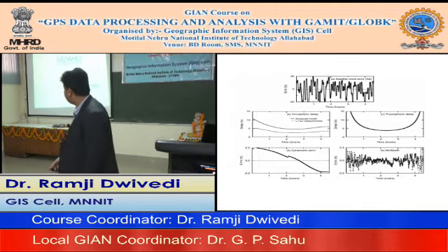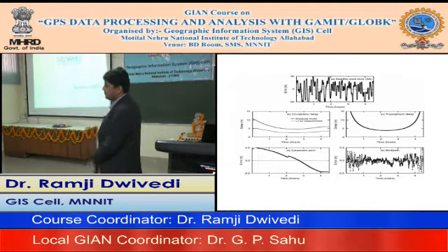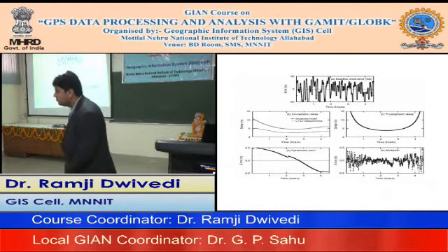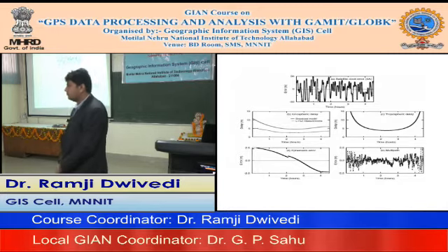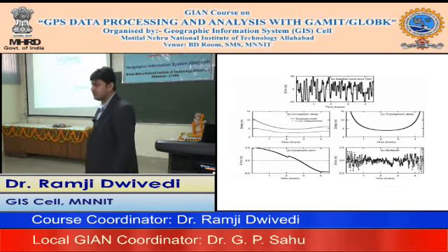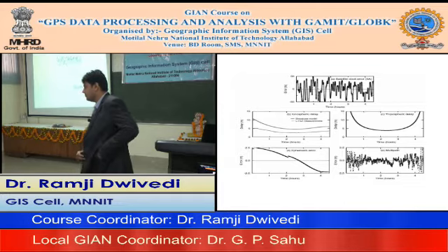And this presumably is relative to a precise ephemeris. So you could actually do this yourself. You have all those broadcast ephemeris files. The interface control document for GPS tells you how to take the numbers in that file and convert them into XYZ coordinates. And you could difference them from the SP3 file coordinates and just see how they behave. In fact, we have software called OBDIF in the software package which allows you to difference SP3 files. So you could play around with this.